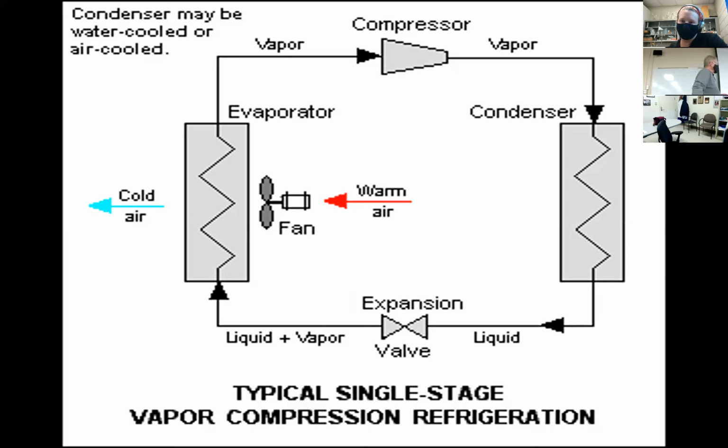That warm air is blown with a fan across an evaporator, and exactly what is occurring is the evaporator is the right term. Your liquid refrigerant, or liquid vapor refrigerant, I'll explain why it's vapor in here, but let's say as much liquid as possible flows through the evaporator.